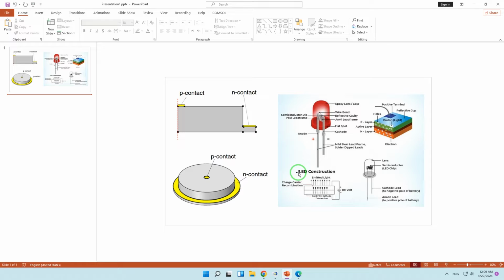Okay. Here we have a device that is made of a 60 micrometer diameter circular chip of gallium arsenide, and due to the crystalline nature of the semiconductor material, actual LED chips are likely to be fabricated using rectangular chips. Only the circular active region formed by the P and N type doping is included in this simulation.